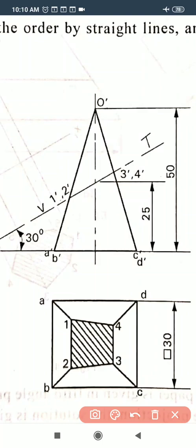And then after that, use the HB pencil and darken this portion. After cutting, this apex is not visible, so give the hatching in any direction, like this or in that direction. And then from this point to all the corner points, those edge lines are visible, remaining lines and base lines are this. So darken those lines. So finally this is the top view of that sectional view.